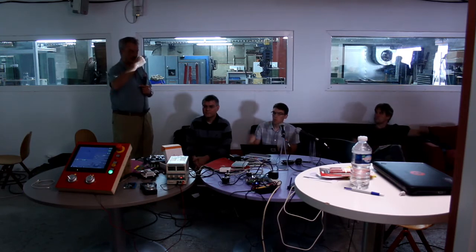However, if you employ a robot arm, let's take my arm as an example, I have a couple of joints here: 1, 2, 3, 4. The positions of these joints do not correspond to the Cartesian position of my fingertip. So a transformation is necessary between the position of my joints and the position of the tooltip, or fingertip in that case.